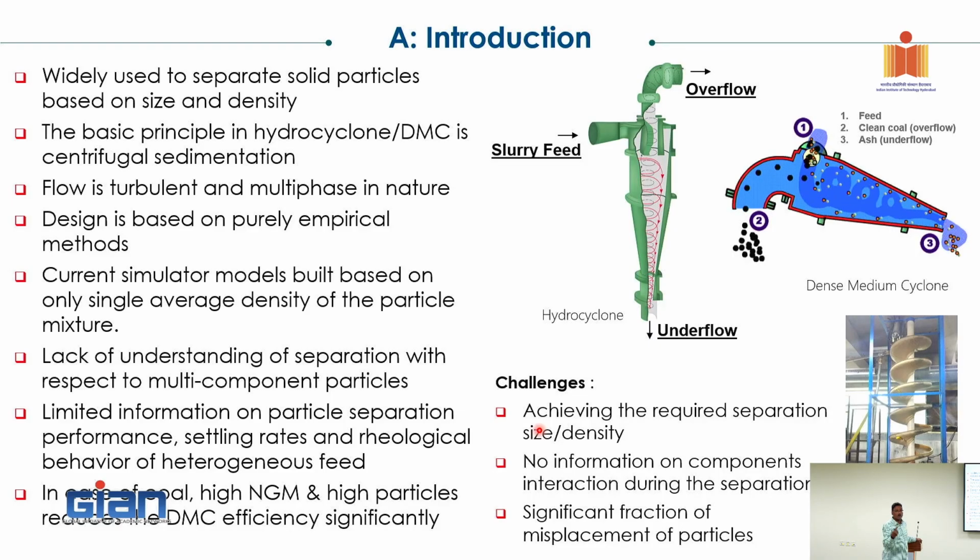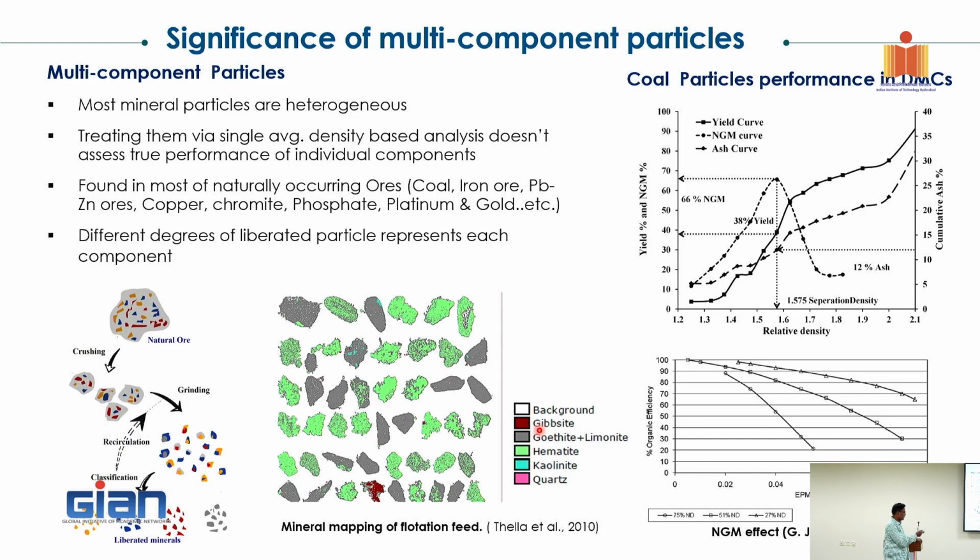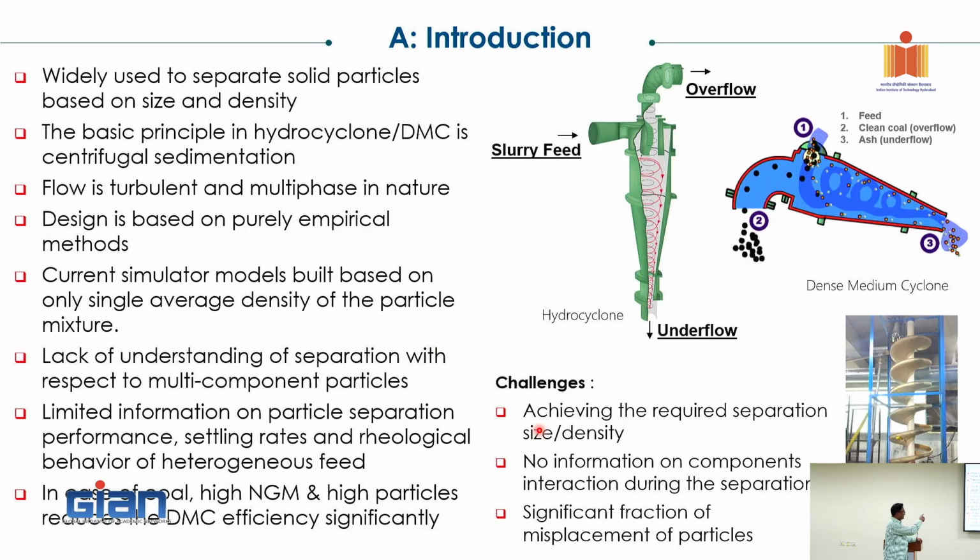So recently, one of our PhD graduates, Mandakini, has done a lot of work on that. I think I'm taking those contents here. And also a significant fraction of the misplacement of the smaller size but heavy density particles is coming to the underflow. So those we are going to look at, and we'll be focusing on three aspects, as I said: hydrocyclone, dense medium cyclone, and spiral concentrator.